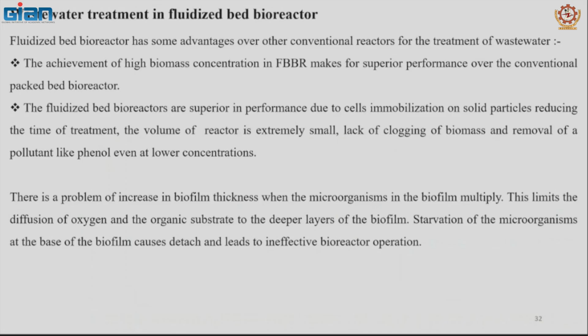Now wastewater treatment in a fluidized bed bioreactor. So the advantages of the fluidized bed bioreactor we have already discussed. The problem with that is the increase in the biofilm thickness when the microorganisms in the biofilm multiply.